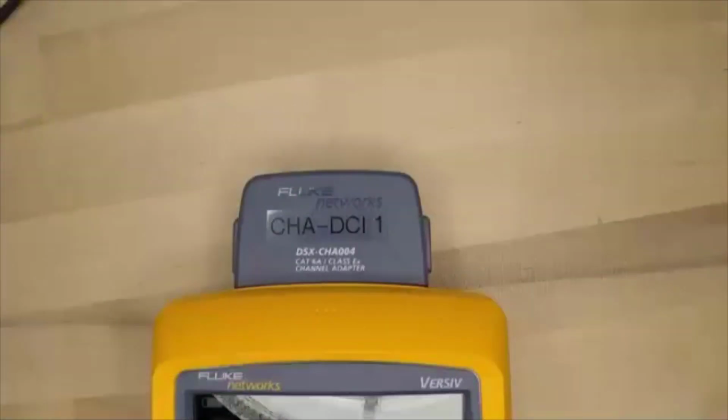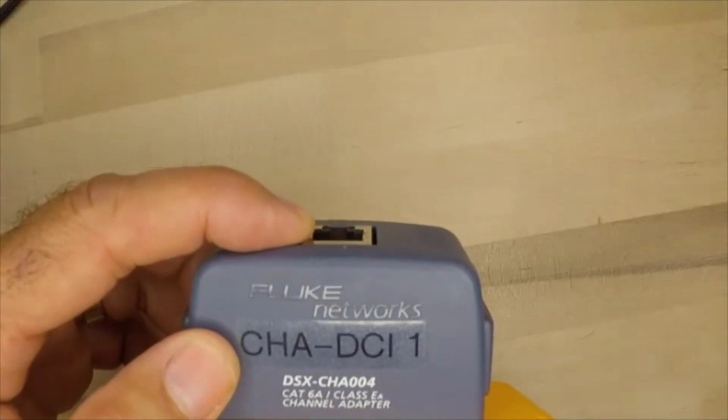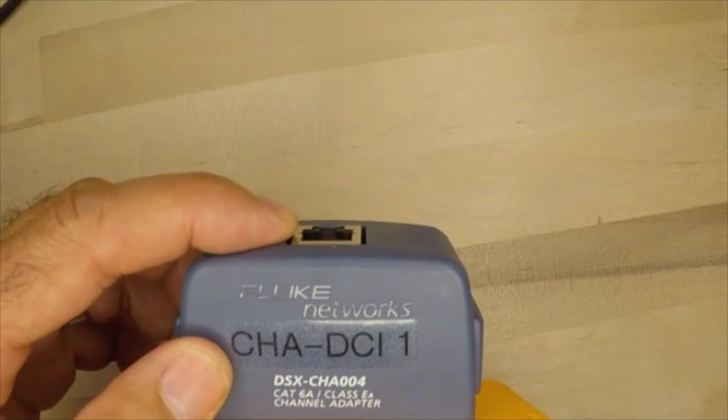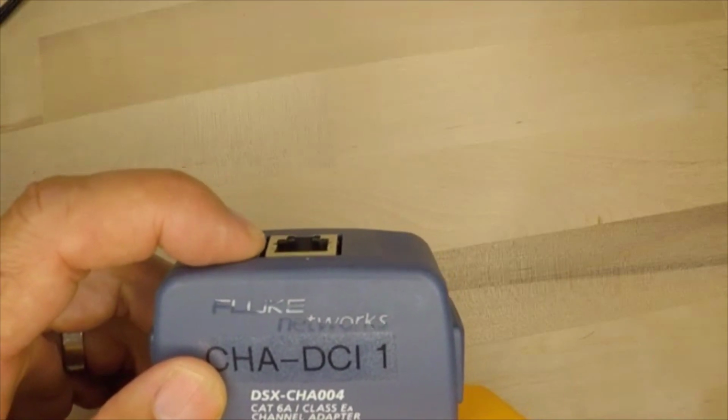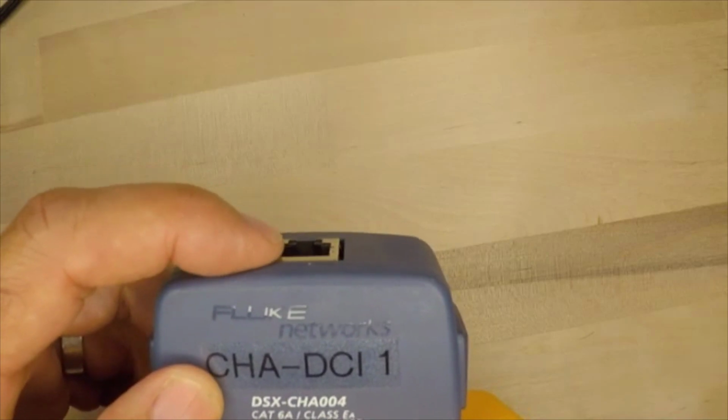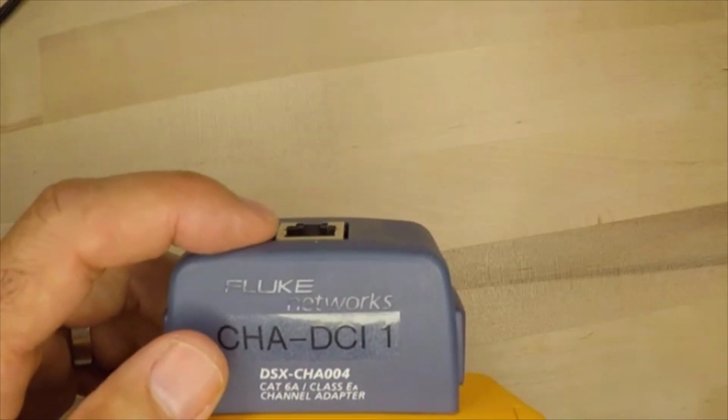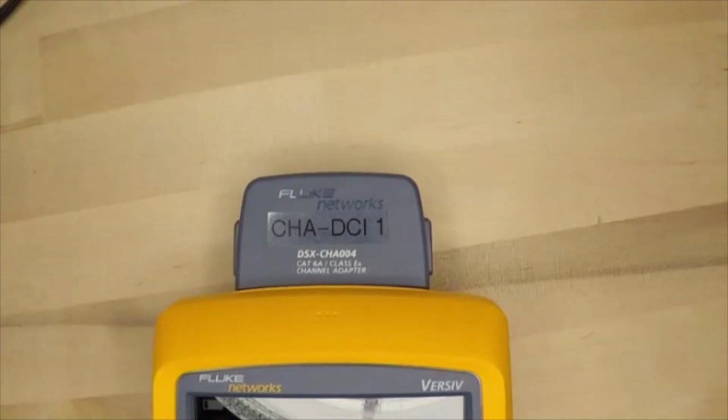I'm going to switch back over to the GoPro because I want to bring up something we spend some time on in class. With our channel adapter right here, when we do our test, this connector right here is not evaluated. We do not evaluate the near-end crosstalk on the RJ45 jack or plug when we use the channel adapter. That is why we do not use the channel adapter for testing patch cords, because we will ignore that RJ45 plug and all we're testing is the cable. And if all you're testing is the cable, well, that's going to be pretty easy. In this case, I'm interested in the cable.